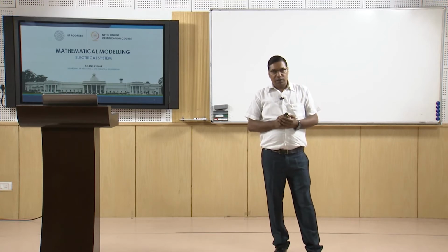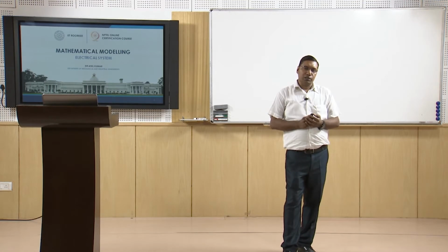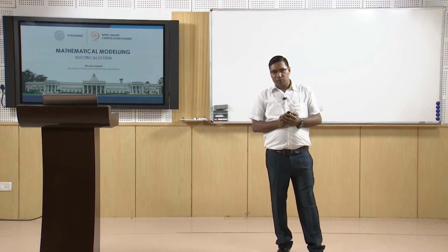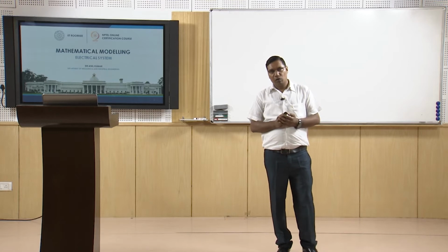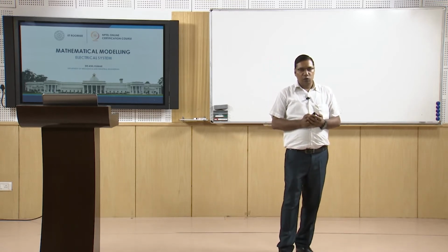In mechanical systems we applied Newton's law to write the differential equation of the system. In electrical systems we use Kirchhoff's two laws, that is the current law or node law, and the voltage law or loop law.